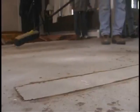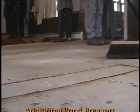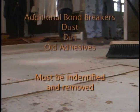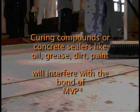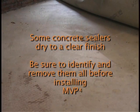Next, test the subfloor for the presence of any sealers or coatings. Additional bond breakers such as dust, dirt, and old adhesives must be identified and removed accordingly. Curing compounds or concrete sealers, as well as contaminants such as oil, grease, dirt, and paint, will all interfere with the bond of MVP4. Some concrete sealers dry to a clear finish and are very difficult to visually detect.